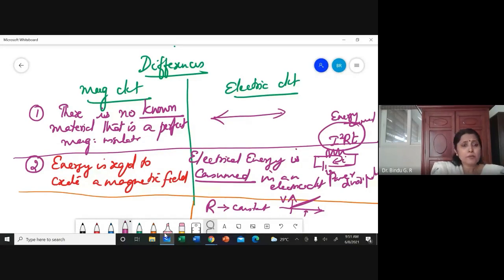It is a slope. But what about reluctance? Now, if I have a BH curve, it comes like this. I am sure all of you have learned. There is some part like a saturation. It is not always linear. As a result of this, the flux is also not a constant. Flux is not a constant means indirectly reluctance is also not a constant.